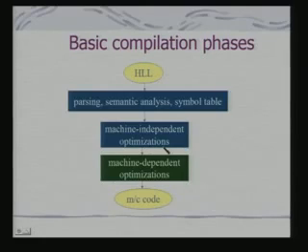Say for example, if I am switching from ARM7 to ARM9, architecturally ARM7 and ARM9 are different. If I already have an application coded in C, and if I can use an appropriate compiler to translate your application in an optimized fashion for the target ARM9 processor, then the cost that goes into recoding of the application disappears.